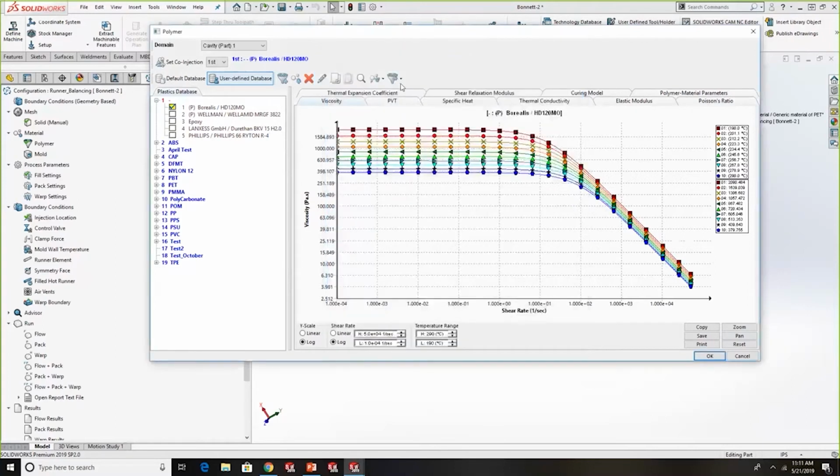The other thing I'll point out, those of you who've worked with Moldex or Moldflow, one of the things you probably recognize from those softwares is you can import bin files. If you've been working directly with a plastics manufacturer, they might send you a bin file. You can actually bring in that bin file. Or some of the new things you're seeing are actual Excel sheets where you can actually import those values into the database. So ultimately, if it doesn't fall within the 4,000 materials in the database, you still have the ability to key in that custom polymer.